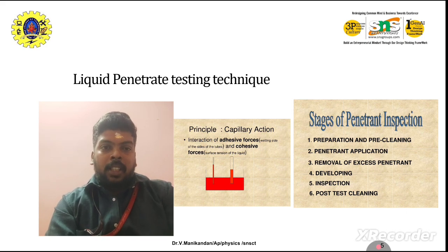Capillary action is based on adhesive and cohesive forces. The stages of penetrant inspection are pre-cleaning, penetrant application, removal of excess penetrant, developing and inspection, and post-test cleaning.